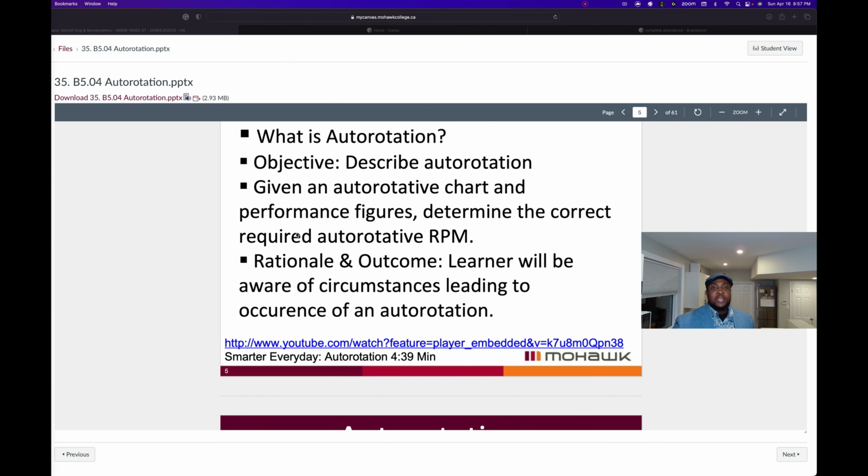One blade leads while the adjacent blade lags, causing an unbalanced centrifugal force, and we say that this is known as blade bunching. This moves the center of mass away from the axis of rotation and causes a wobble in the system. The out of balance condition can escalate quickly into circular gyrations that eventually lead to structural damage, and the damage can be quite devastating.